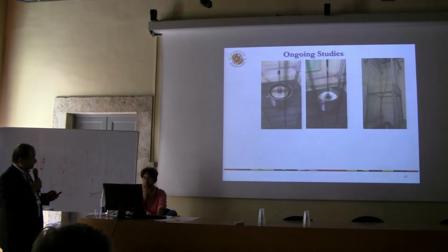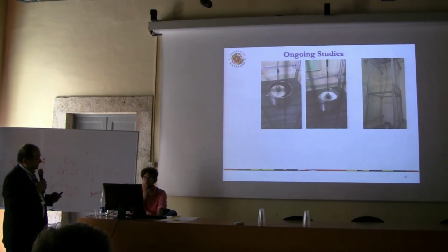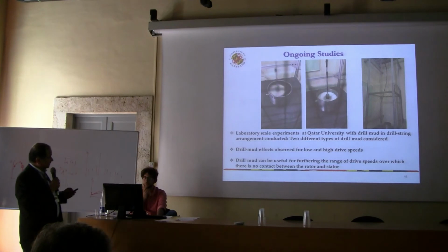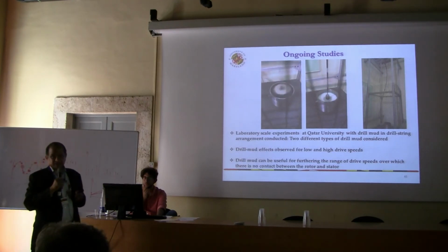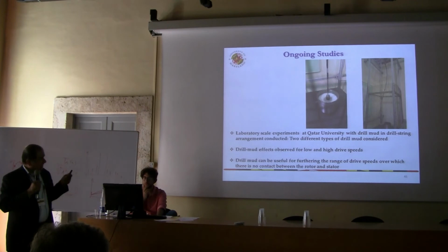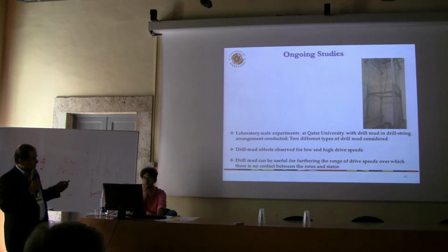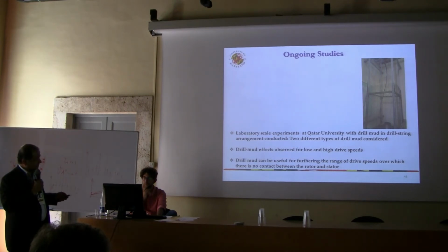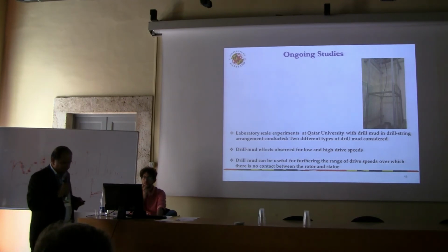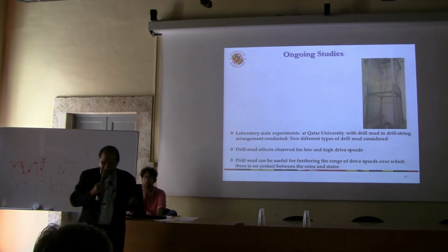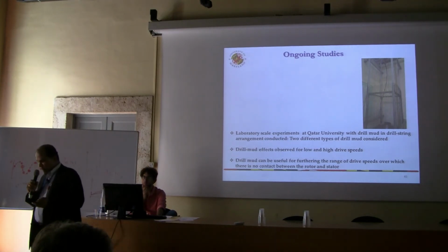So in terms of future work, this is a study that we've been doing with Qatar University, where we have a similar setup at Qatar, and what you saw before was without the drill mud. With the drill mud you see a stabilizing effect as well, and the backward whirling can be quite dangerous. In this case, it was so severe that the whole drill string setup came out of the borehole itself. So again, this is ongoing work with the drill mud, which has a big influence on the dynamics. Of course, the damping, as I mentioned before, will be useful to reconcile with as well.